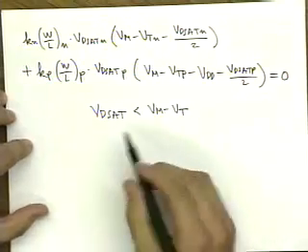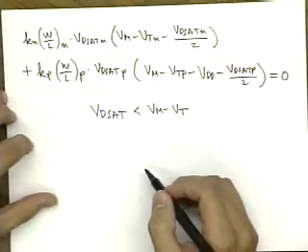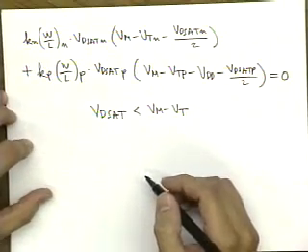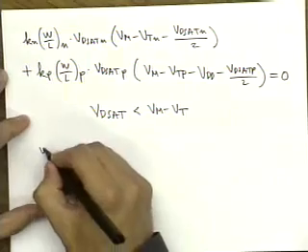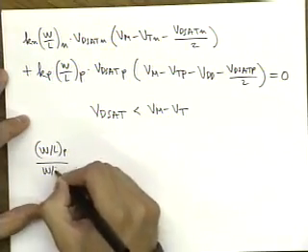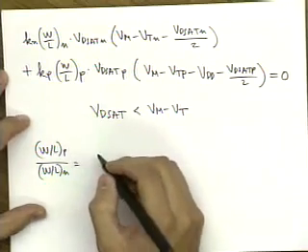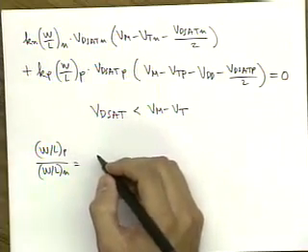So it's basically just to first figure out the methodology, and then when you get comfortable later on, you can put in more complicated effects. But what's interesting here is to derive this W over L ratio in terms of switching threshold.